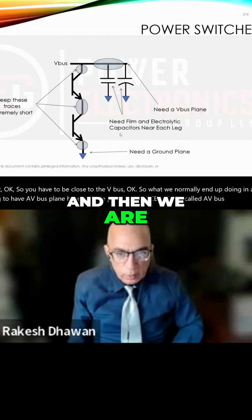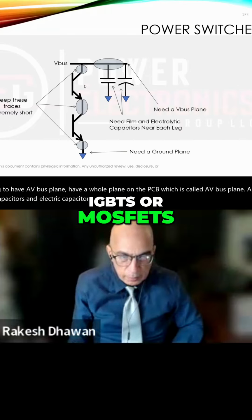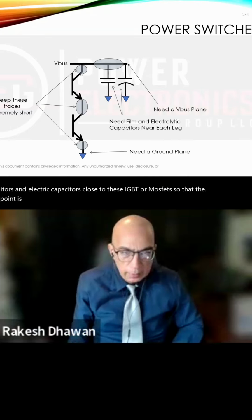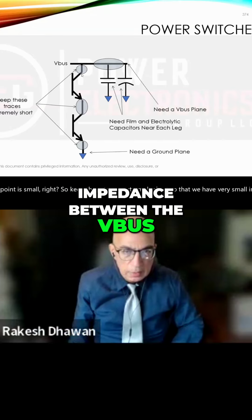And then we also use film capacitors and electrolytic capacitors close to these IGBTs or MOSFETs so that the impedance between this point and this point is small, right? So keep these traces extremely short so that we have very small impedance between the VBUS and the drain of the top IGBT.